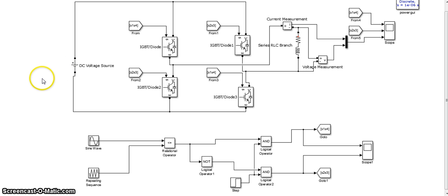During the next phase or cycle of IGBT, S2 and S3 are triggered by giving trigger pulses to the gates of the IGBTs. During this period, the input voltage is applied at the output but in the negative direction. The current conduction starts from the supply, goes to S2, S3, the load, and to the negative of the supply. As the two cycles continue, the positive and negative voltage is applied at the load and the current direction changes in the two cycles. As the current direction changes, the alternative voltage is obtained at the load, thus converting DC